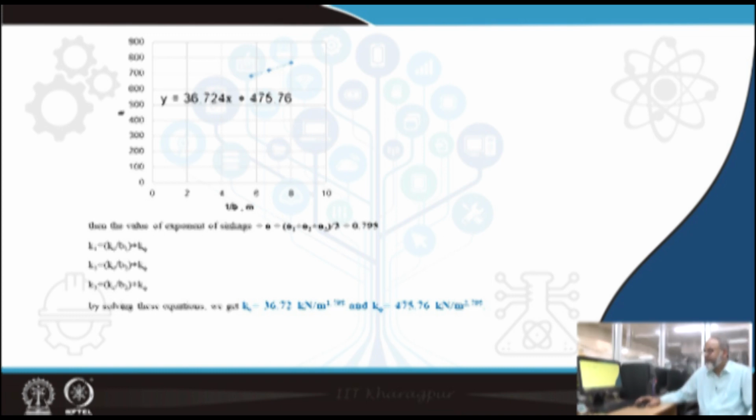So we have utilized this plate penetration test, and then we tried to find out the exponent of sinkage and the modulus of sinkage. Again, modulus of sinkage is nothing but your cohesive modulus of sinkage and frictional modulus of sinkage. So these are the three values which we obtained by carrying out the plate sinkage test.